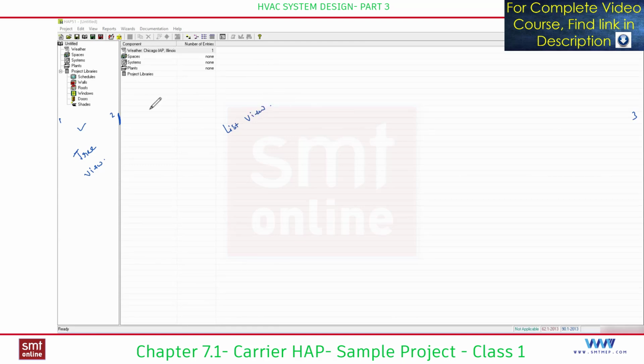You can verify here. After saving the name of the project, you'll find the name of the project here. Under the project, you'll find weather, space, system, plant, etc. So this is like a main, and these are the branches, like a tree view. And on the right side you can find the space, system, etc. list. When you select the space, you'll find the list of the spaces. When you select the system, you'll find the list of the systems. And you can double click the space or system to get a pop-up window, and that can be used to edit.